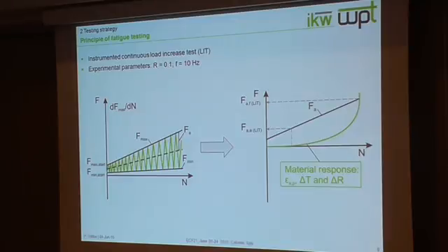What we are trying to get out of our measurement techniques, adapted during the test with the specimen, are some fatigue properties during this load increase. The first one is, of course, the failure amplitude, the force amplitude at failure, the fracture of the specimen. The second one is, if we analyze the material response of our measurements, the transition point from a nearly linear slope to an exponential slope.